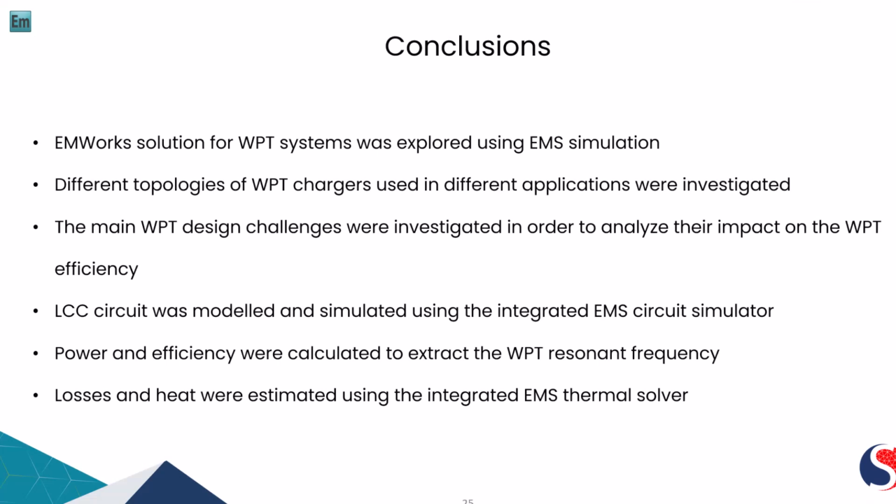So, in conclusion, the EMWorks solution provides a powerful platform to design and analyze wireless power transfer systems. The different topologies of wireless power chargers used in different applications were successfully explored and analyzed using EMS simulation. The main wireless power transfer design challenges, such as misalignment tolerance, coupling coefficient, and EMF exposure, were also investigated. The LCC circuit was modeled and simulated using the integrated EMS circuit simulator to improve the efficiency of the system.